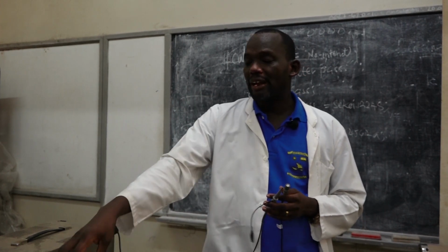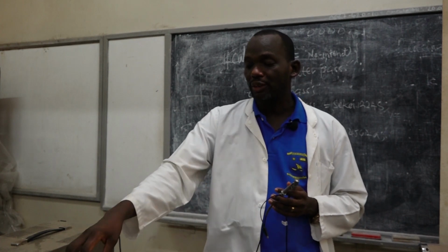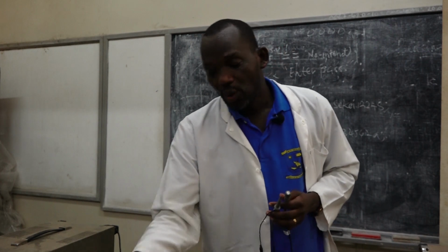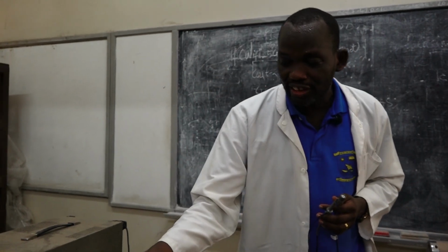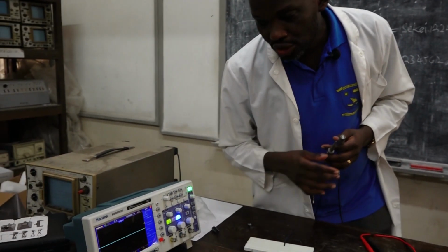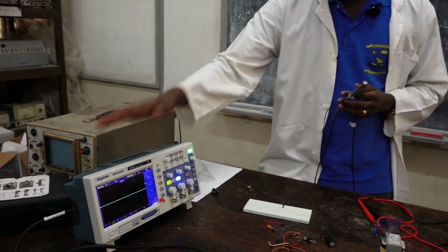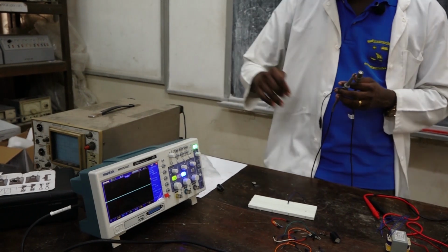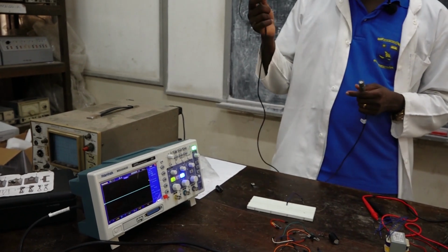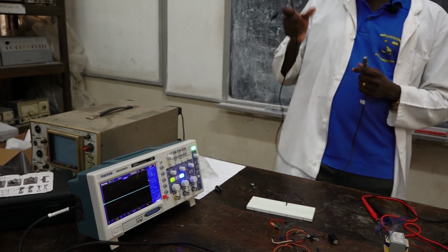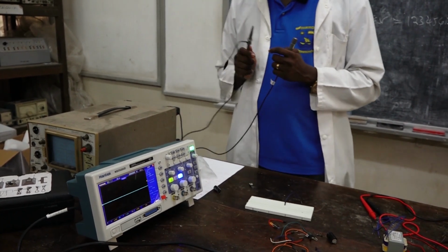According to the manufacturer, as explained in the user manual of this digital oscilloscope, whose name is Hantek MSO5202D, you have to make sure that the probe attenuation setting is times 10.